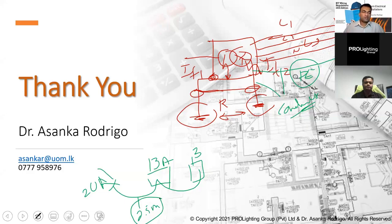Yeah, normally, these concepts like the test point and the separate earths came with the practice of the TT system. If you're going with the TT system, your earth electrode resistance is a matter, because the standard tells us what type of earth electrode resistance is needed for a TT system. For example, in an electrical requirement, your earth electrode resistance should be less than 200 ohms for a 30 milliampere RCD protection. Likewise, that is mentioned only for the TT arrangement.